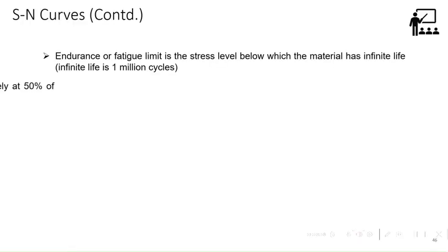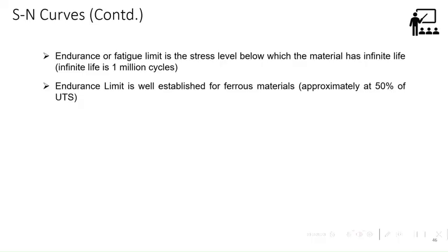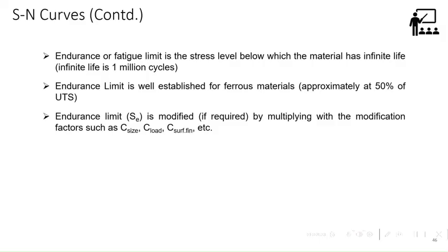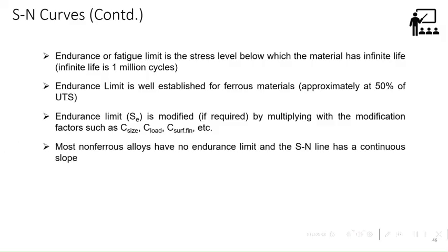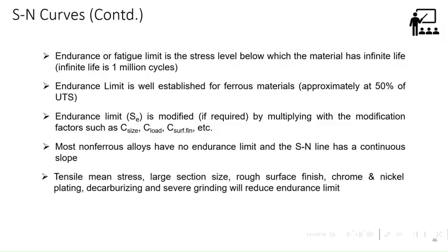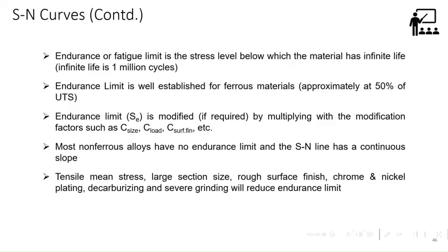And again, your endurance limit is at 10 to the power 6, and it is also known that the stress at 10 to the power 3 for ferrous material is about 90%. I'll show you more detail down the line. But the endurance limit at 10 to the power 6 has to be modified. No changes occur at the 10 to the power 3 point due to load, size and surface finish, only the endurance limit. And for non-ferrous materials, there is no endurance limit. For that you usually consider 5 times 10 to the power 8 to apply your correction factor.